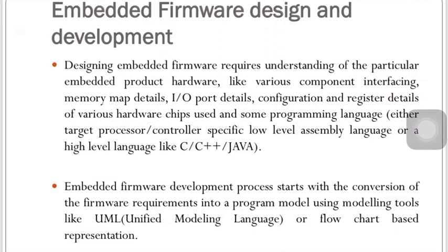We can take an example of what we do in the lab. Simply, we are writing a code for a stepper motor, right? So first we need to know which microcontroller we are using and which pins of that microcontroller we are connecting the stepper motor to, right? And what registers of that microcontroller need to be configured to access those pins, right? If we know that, then only are we able to write a code for that embedded system or that task. Yes or no? So if we know all this, then only can we easily write a firmware for that.